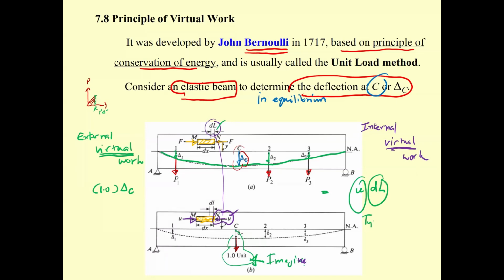It depends on the type of structure. The equation for this term will change based on the type of structure. For the truss, the U is going to change to the small axial force n, and then for the truss you have delta equal to NL over AE.